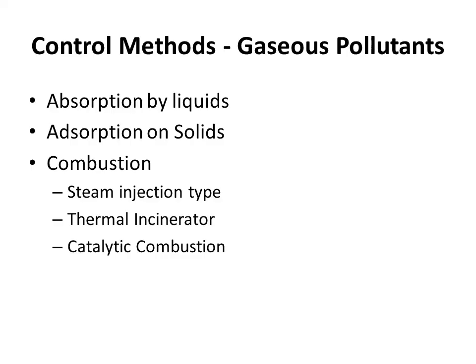Till now, we have seen the various methods of controlling the particulate matter. Now, the methods used for controlling the gaseous pollutants are mainly absorption by liquids, adsorption onto solids, and combustion methods. The combustion methods mainly include steam injection type, thermal incinerator type, and catalytic combustion.